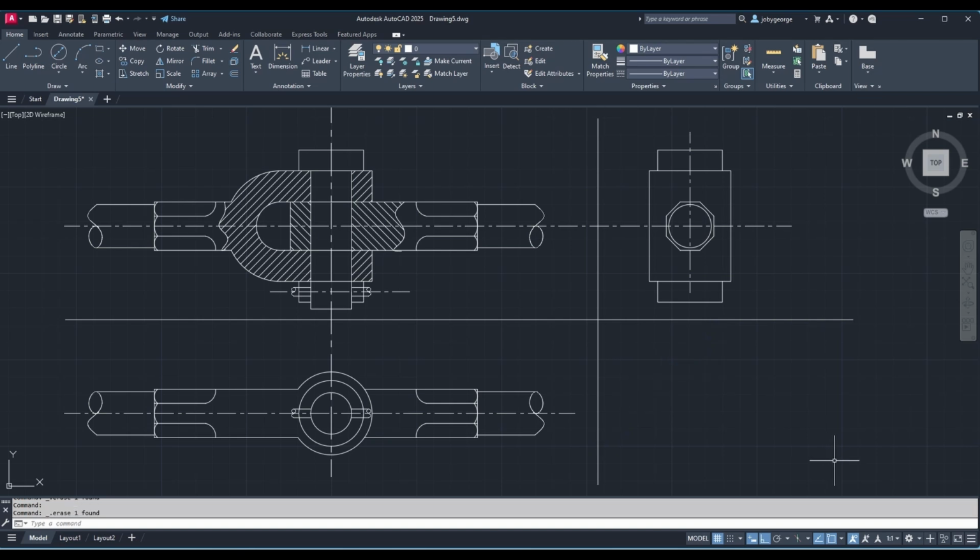Okay. Now I need to draw the bottom portion of the pin, the center line, and just copying about that point and keeping on the center. In the vertical center I'm just pulling it downwards up to the XY line. Now this also I can project and do, so I'm not doing that.